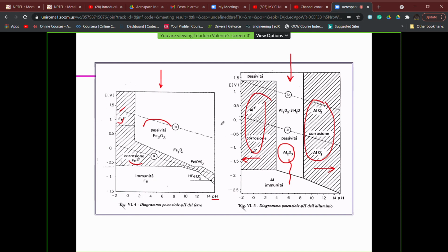but also for the corrosion rates, there do exist specialized handbooks which are able to tell us, for certain materials, for a certain working environment, according to the experience in the field, how high the corrosion rate can be, depending on the corrosion form which can develop. So also in this case, apart from new formulation, we do not have to do too much effort, because the values of the corrosion rate with the specification I told you before are already known.